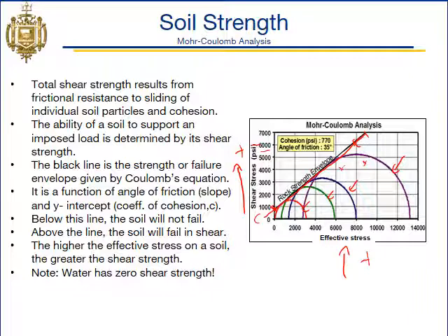So big note here too is that water has zero shear strength. So by adding water to a soil, you can't really make it any stronger, because it doesn't have any ability to add shear strength, because it itself doesn't have any shear strength. Imagine trying to make a pile of water like we had a pile of sand on that last slide. It would just make a big puddle. So water does not help with the strength of a soil.